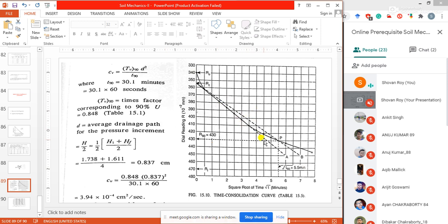So this tangent line is extended at the tail portion and the starting portion to find the actual corrected reading, because initially, due to voids, soil behaves differently; soil is not linear, it behaves non-linearly. Due to this non-linear behavior we have to calculate the correct reading, and only using this straight tangent line can we calculate the correct reading of consolidation of the sample.